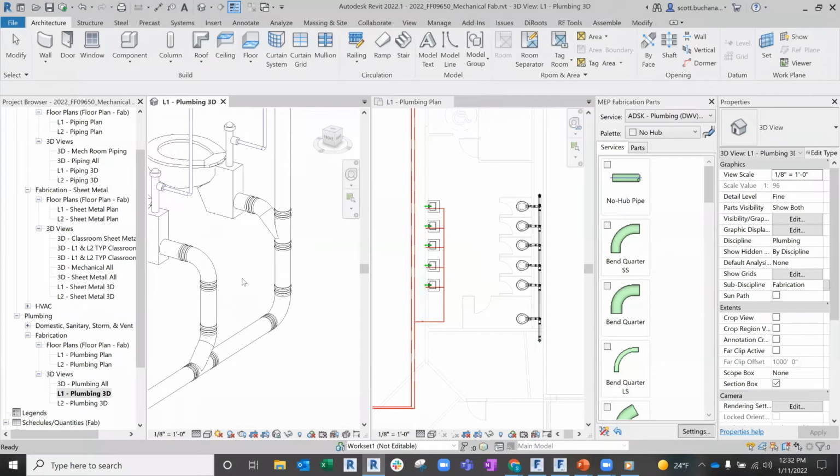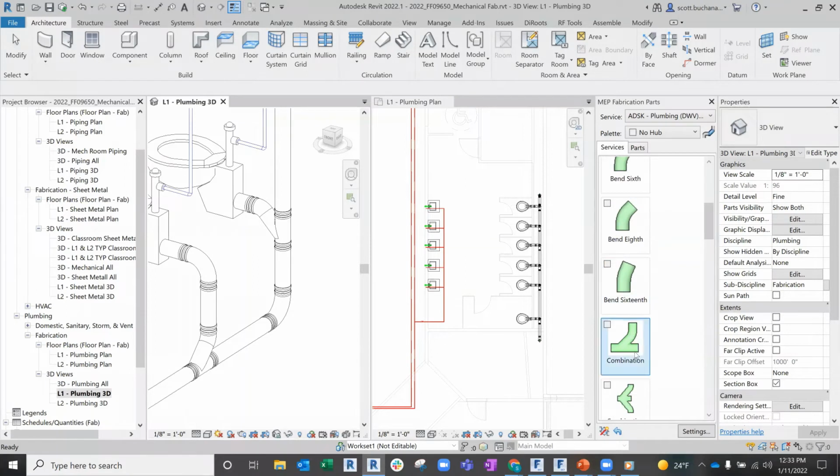So what I wanted to show is, think back to what I said earlier about the sheet metal. Even though there was a certain type of fitting that was placed, we don't match the engineer's fittings, okay? We just match that there was a T or an elbow or some type of junction. And then it looks at our piping service to understand what should go there. We don't have the ability to say, hey, if you're vertical, put in a sanitary T. It just has to go down through this list and say, where's the first kind of setup junction? Oh, it's a combo, right? If sanitary T had been higher up in this list, then a sanitary T would have gotten used in every single one of those spots, okay?